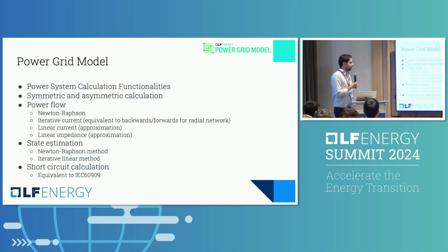Then, a short introduction about Power Grid Model itself. Well, now you know why to use Power Grid Model, but what can you do with it? It has power system calculation functionalities for symmetric and asymmetric calculations, so you can do single-phase and three-phase calculations with Power Grid Model. And we have different calculation types that you can do. So we have power flow, state estimation, and short circuit calculations.